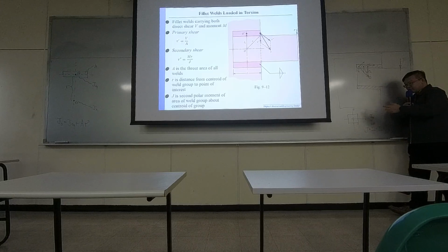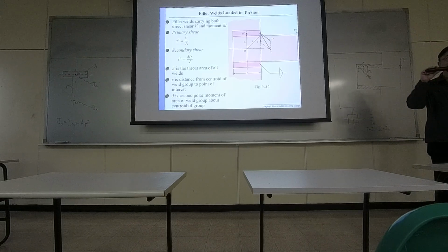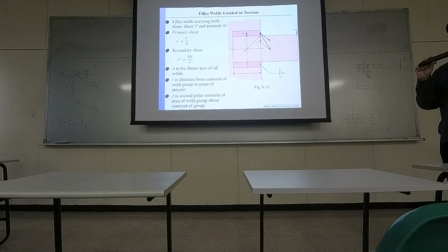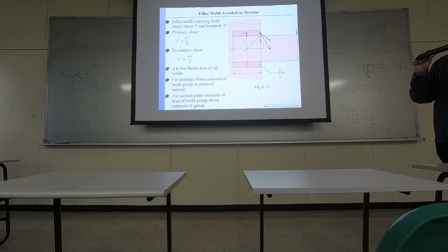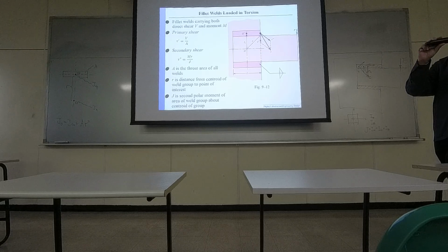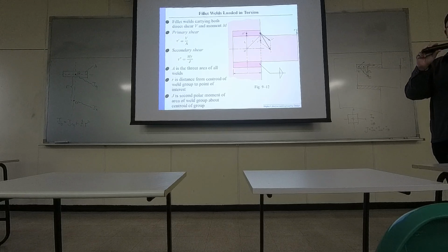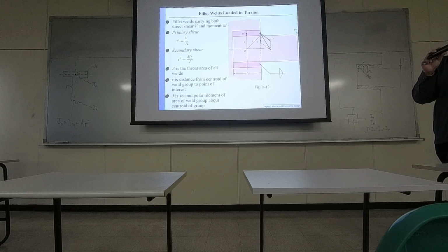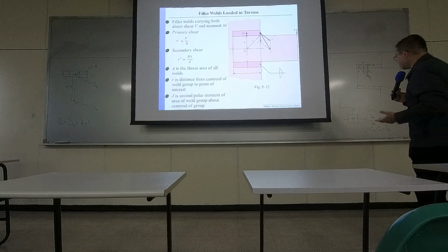So when we have bending, and if you have larger I on that particular rotational orientation, this material, this cross-section area, can fight against this moment better.